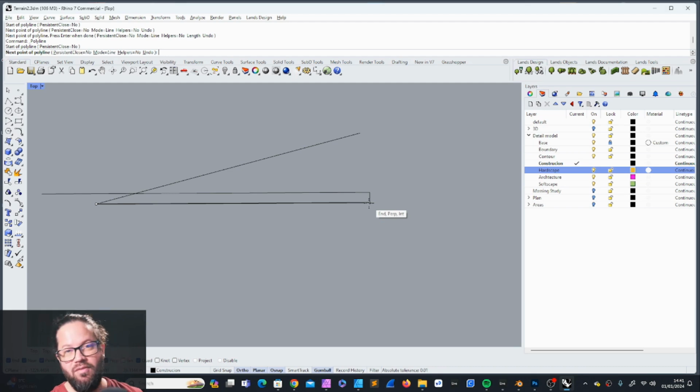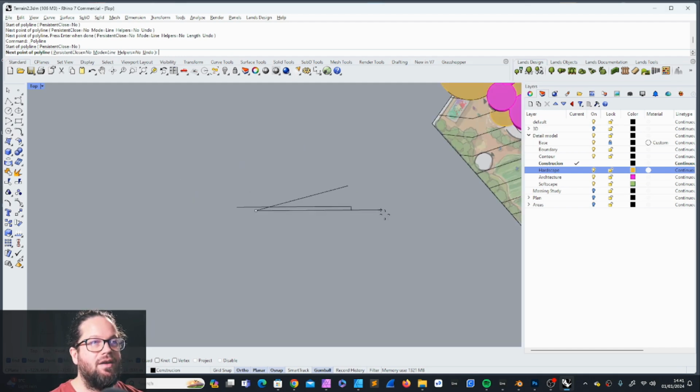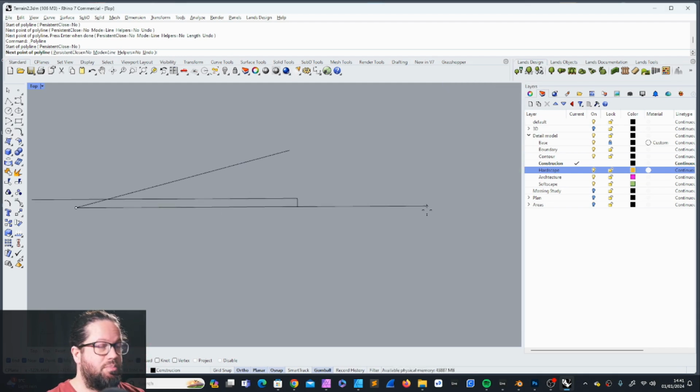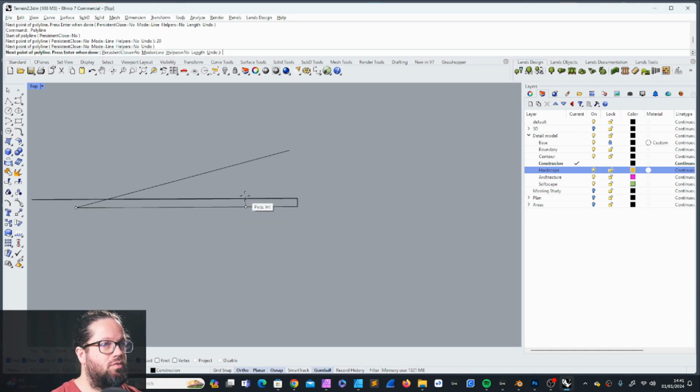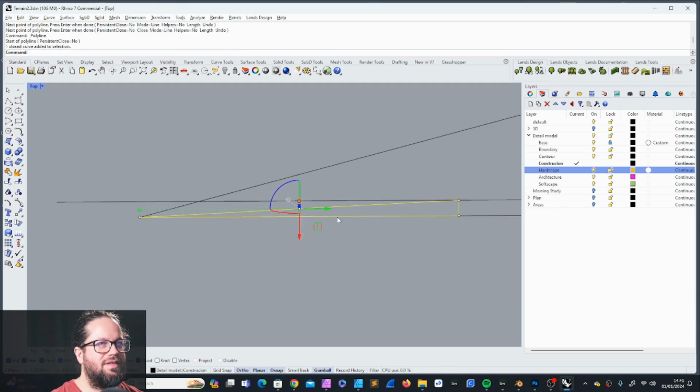Now, this is a private project. You don't need any railing. Sorry, I'm talking about railing. So you need a railing if your slope is steeper than 1 to 20. 1 to 20 is this: 20 meters to 1 meter. This is 1 to 20. This is like a slope which you don't feel too much.